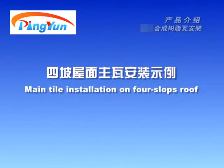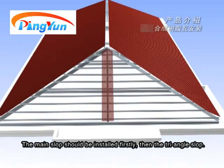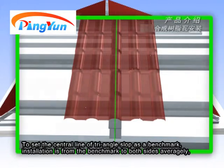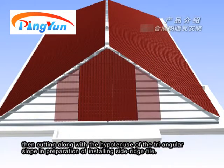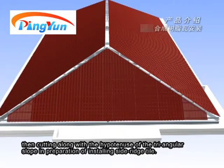Main tile installation on four slopes roof. The main slope should be installed first, then the triangle slope. Set the central line of the triangle slope as a benchmark, and install from the benchmark to both sides evenly, then cut along the hypotenuse of the triangular slope in preparation for installing the side ridge tile.